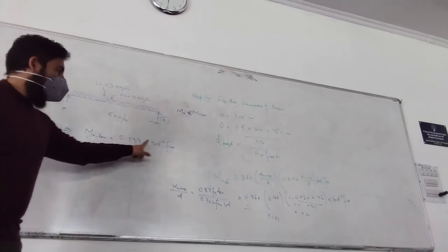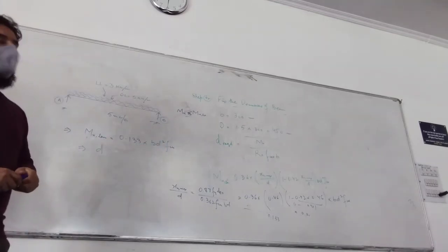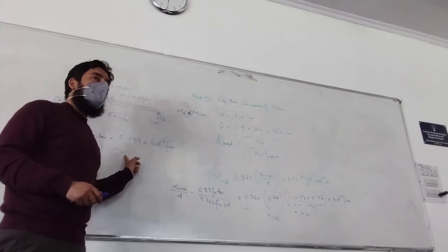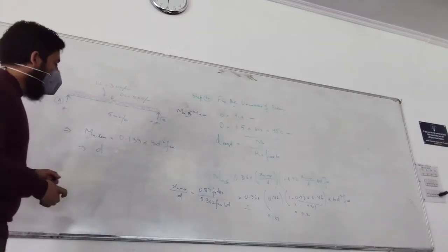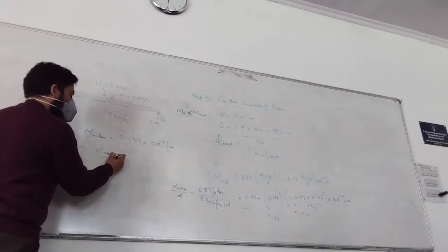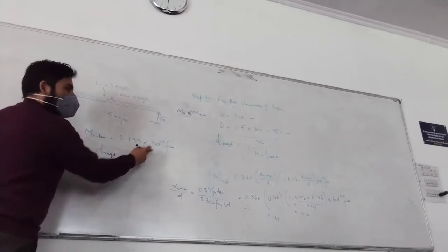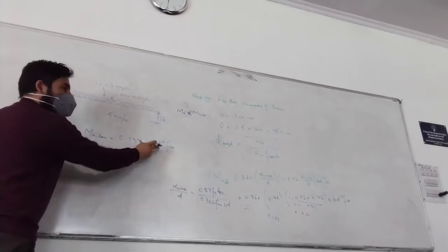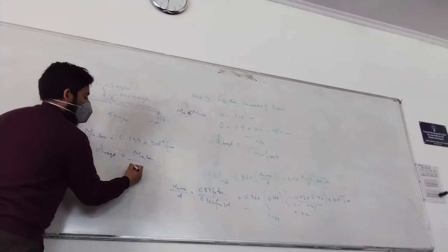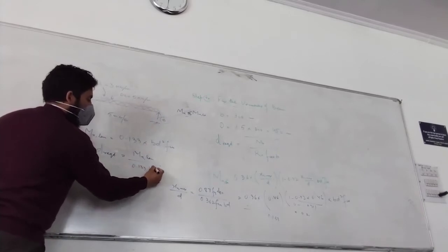So Mu limiting is equal to this value. Now your Mu cannot cross this value when it's a singly reinforced section. Remember. So D will be the D required from here. You can say D required will be the square root of Mu limiting by 0.133 B FCK.